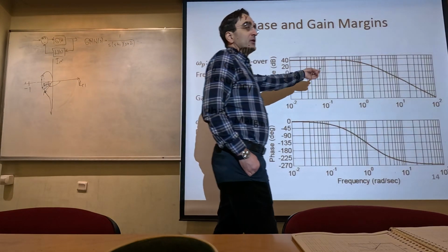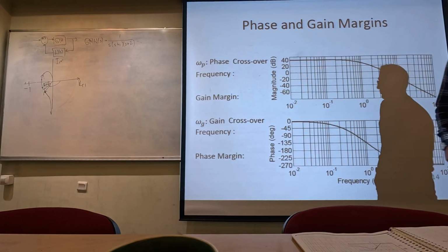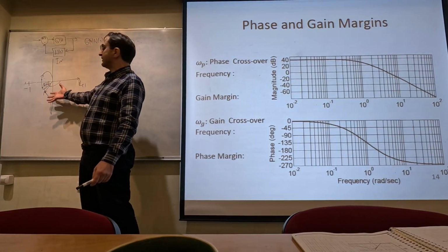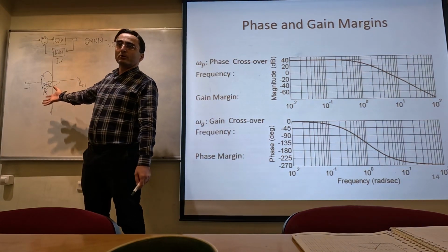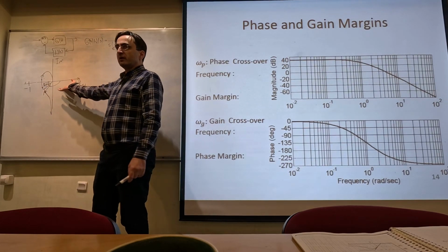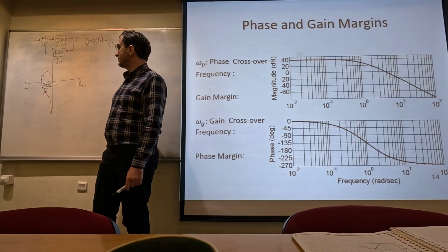In general, we show these in separate plots, which gives us a Bode plot. So this is the same thing. We can plot the frequency response in a polar plot like this, putting the magnitude and the phase in this manner. It is called a polar plot, and it's part of the Nyquist plot that we can draw.